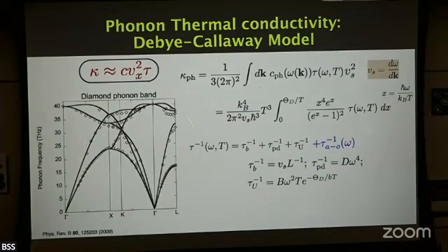Here, they are directly solving the Boltzmann transport equation that Brandon showed last week. And then they get these numbers, and all those things that you can calculate from them. In fact, this paper emphasizes that on top of this, they have to add the acoustic mode and optical mode phonon scattering counts, which is very important.